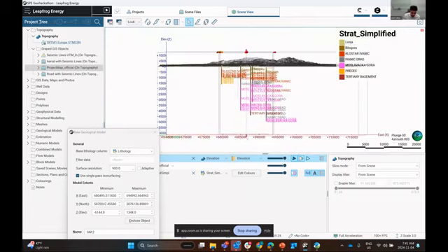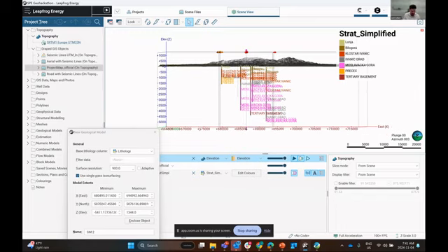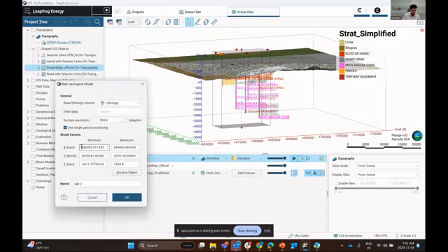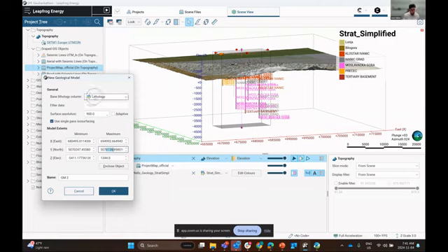We can also extend the bottom of our model to match with a particular depth. So this is good for this particular object, and we can also input the exact eastings, northings, and elevations of the boundary of our geologic model. The base lithology column is going to pull information associated with the categorical information that we define as the base lithology.